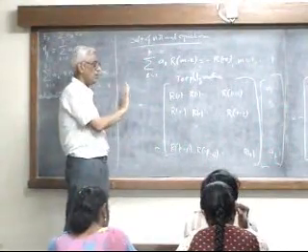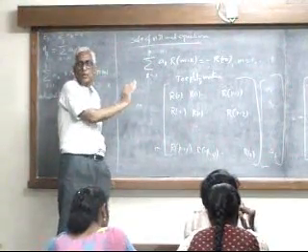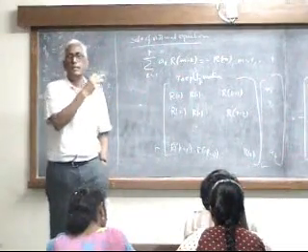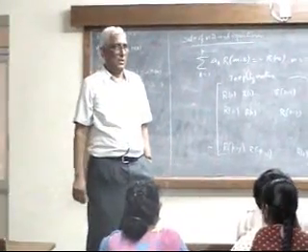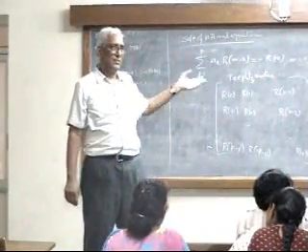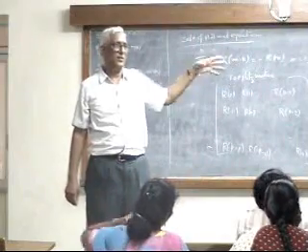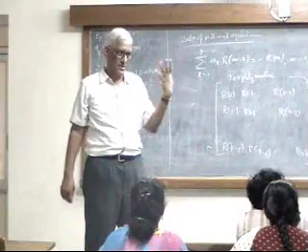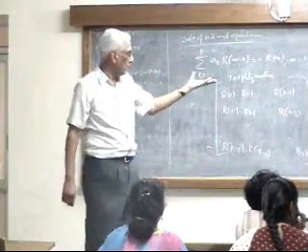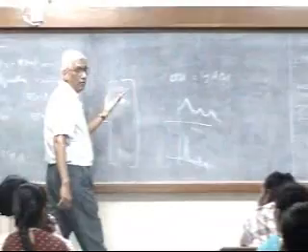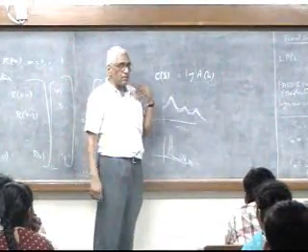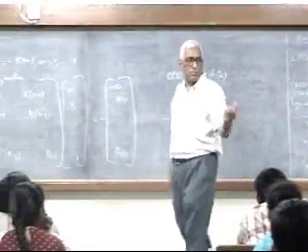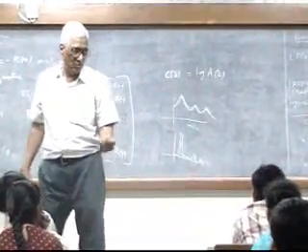But at the same time, I don't want to truncate your thinking by saying, okay, this is what it is, take a_k. But at least you should keep in mind that there is simply so much to look at. What is linear prediction? Where are the area coefficients? Where are the reflection coefficients? Where is the vocal tract shape and so on? It's all very interesting. It goes on and on. Ultimately I have to bring in why all of this: because cepstral coefficients are needed for interpretation, for my speech recognition, for matching, and so on and so forth.